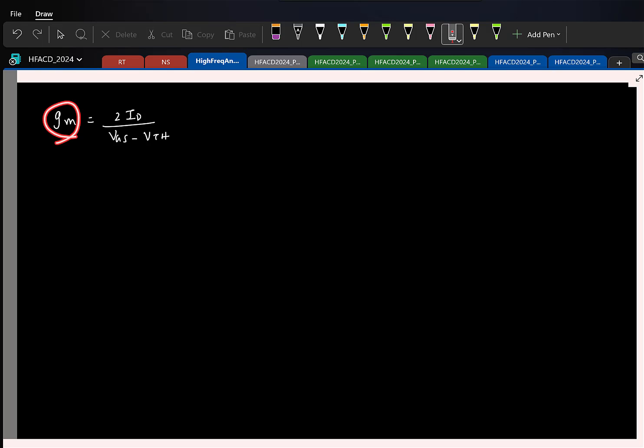Here you have a GM, and remember GM has units of conductance, right? So for reference, what do you think I should use? Some other reference conductance. So that's a resistor. We'll say we want it to be equal to 1 by R. And typically this can be an off-chip resistor that is nicely manufactured so that its value is constant.